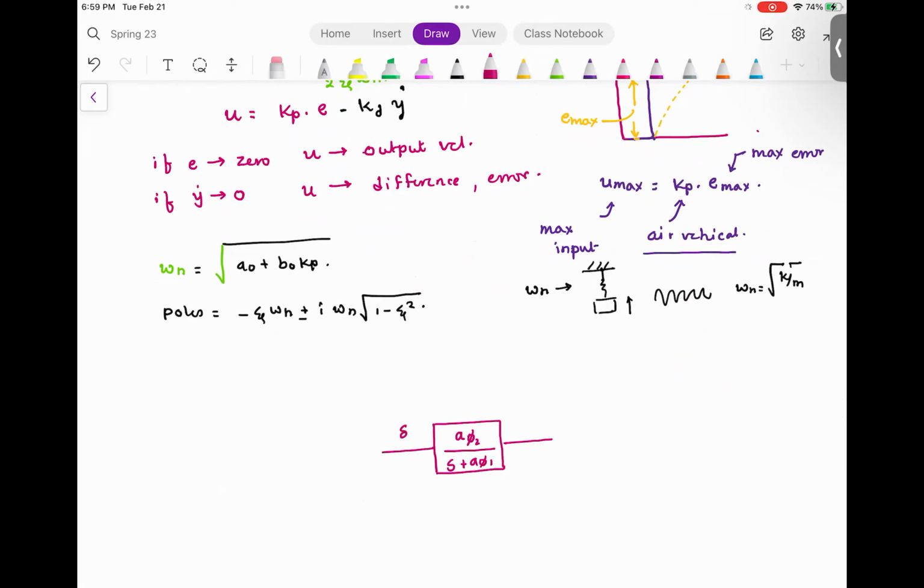Now what you have is the aileron input, and this aileron input is controlling the angular velocity about x. P is the angular velocity about the x-axis of the aircraft. I'm going to add the summing junction, and then I'm going to pull this from here, and add a KD phi term on this.